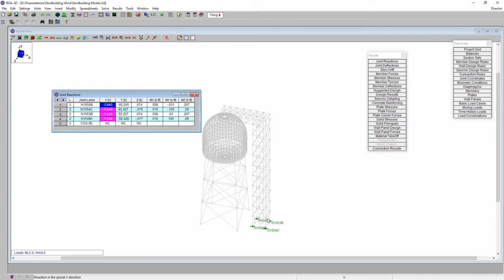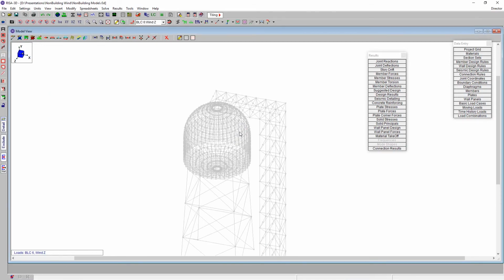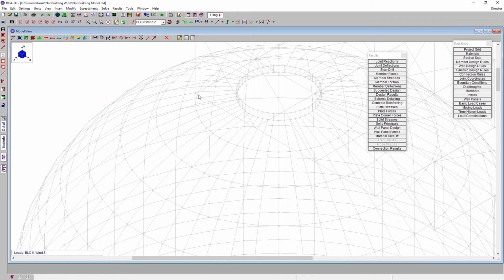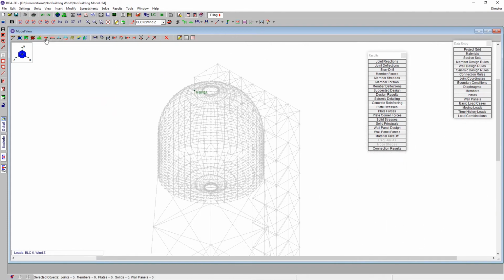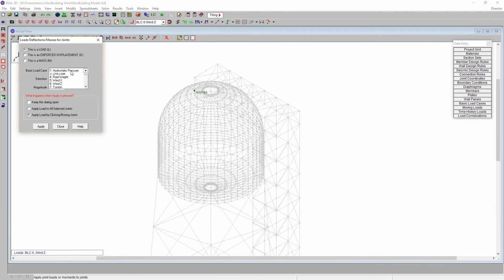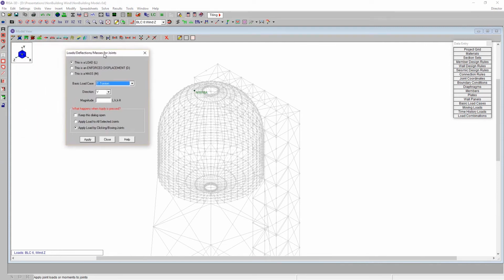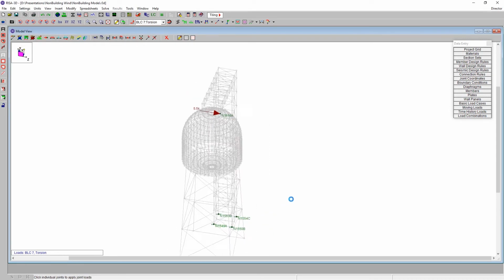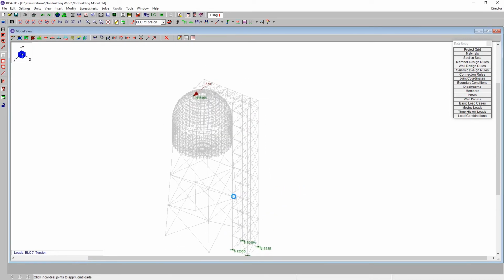And what we recall is that that is going to be multiplied by 0.175 in order to find our torsional point load. And so 31.2 kips times 0.175 gives us a point load that we're going to apply that will act torsionally here. And I'm just going to click on the node where that'll be applied. And that's going to be 5.5 kips. So I'll come up here for torsion, and then we're going to say that this is acting in the positive z direction of 5.5 kips. And so we've put that on there. So that point load right there on that tower is going to twist it.